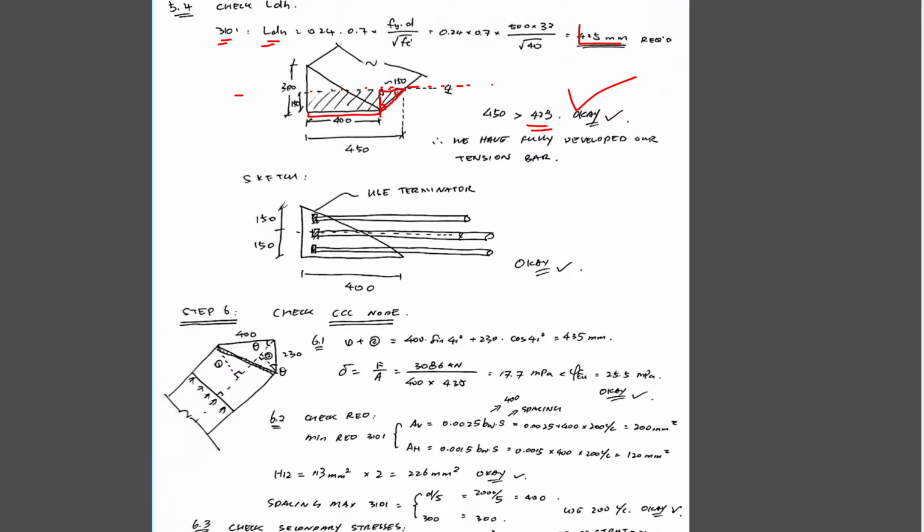Or option 2 is to have a welded plate over here on the side, and this plate will have pre-drilled holes, so you're protruding your bar through, okay, and then you cut it off and then weld it up. Then you can develop your tension bars.